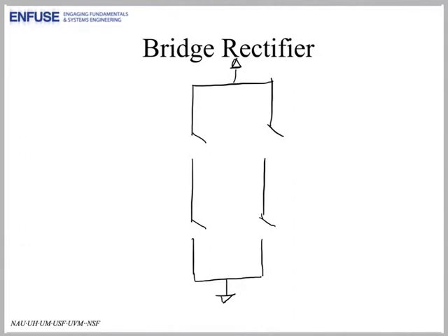Let's look at a specific case of a bridge circuit called a bridge rectifier. This is going to show you how a basic bridge can let us manipulate currents. We'll put our load in, again bridging the two parallel circuit branches. We're going to look at the case where we'd like to use our bridge rectifier to get current to go through this load in two different directions. In order to do that, we're just going to manipulate these four switches.